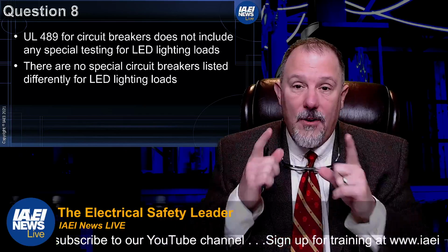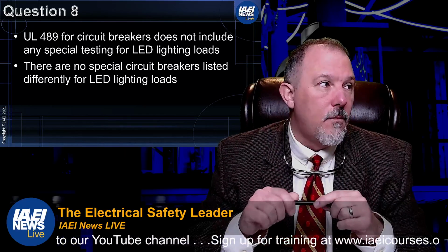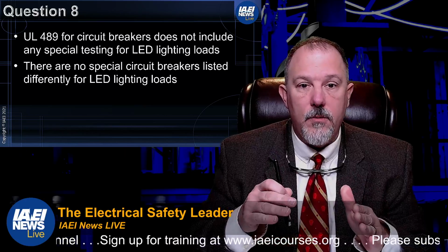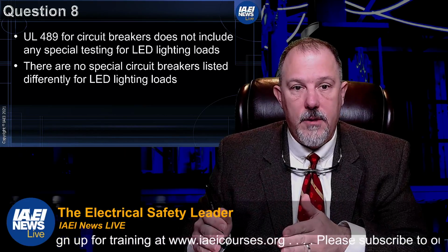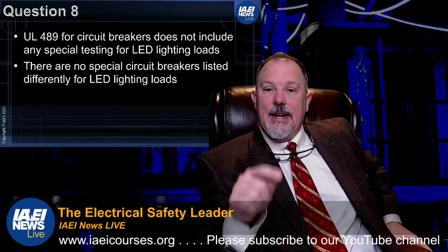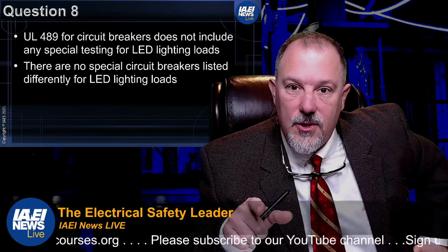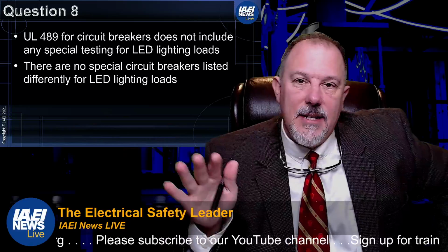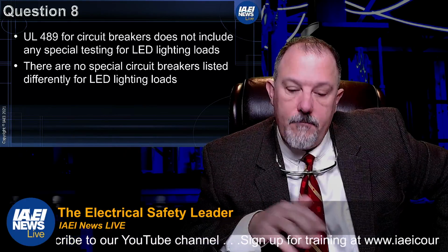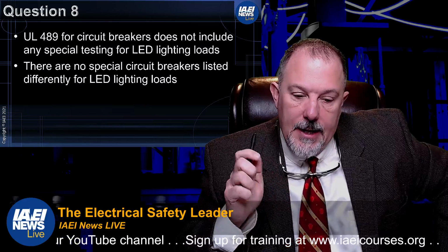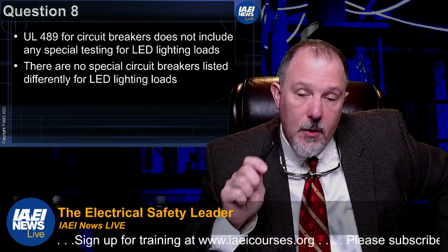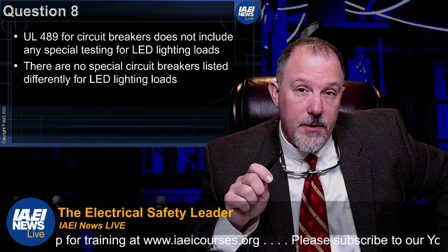What I do know is I've heard people talk about the fact that if they put too many LED lights on a single circuit, when they energize the LED lights, they have tripped the molded case circuit breaker. And that is purely because of inrush currents.